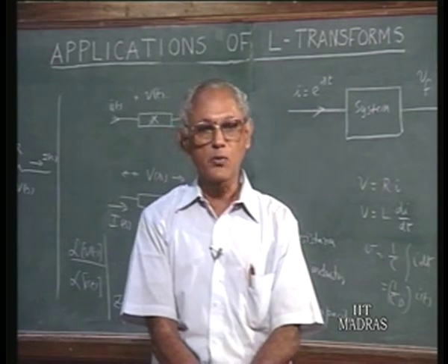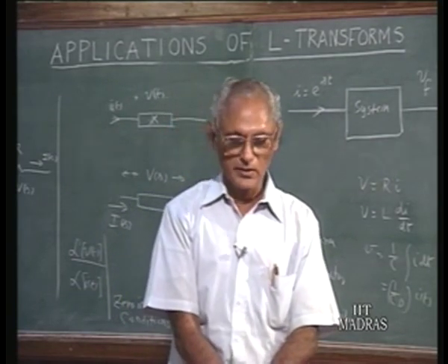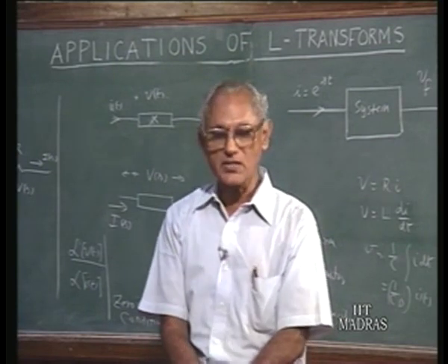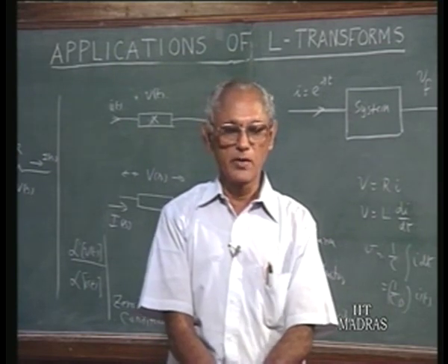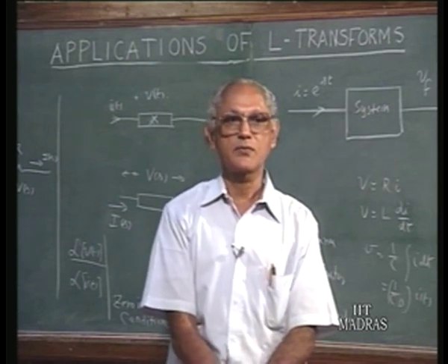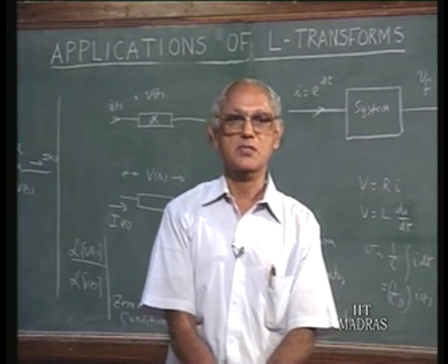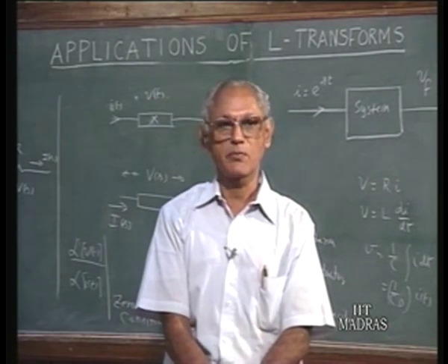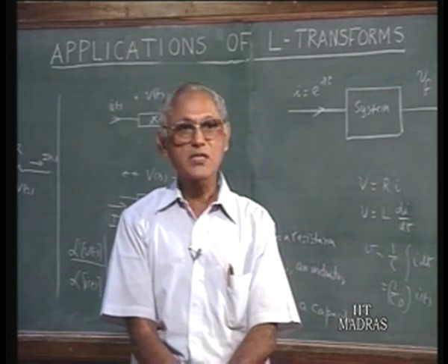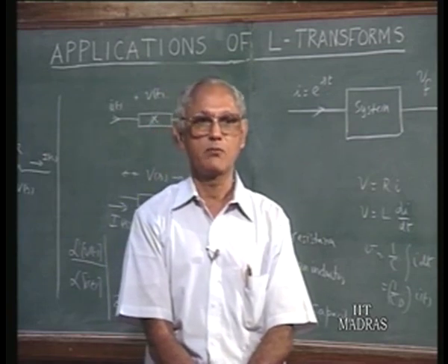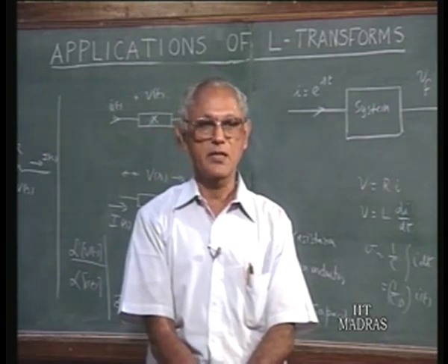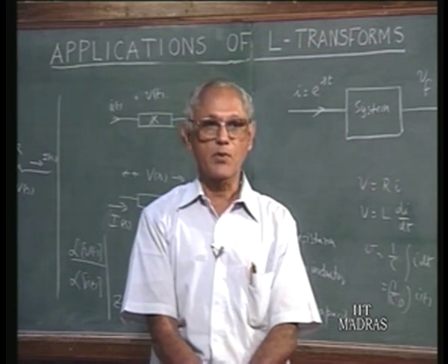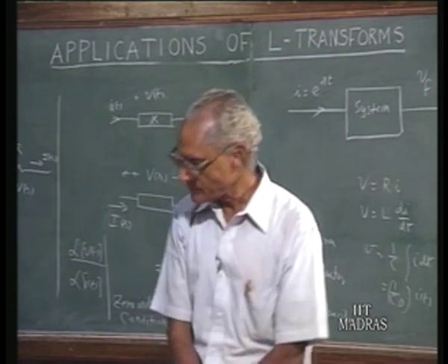the approach is very similar to what we do in the case of AC circuit analysis. We deal in terms of transformed variables instead of phasors. We deal with generalized impedances instead of sinusoidal steady state impedances. That is, wherever j omega occurs, we use S instead of j omega. That is the only difference. So this will be illustrated by means of an example which we will now take up to illustrate the technique of the Laplace transform to the transient analysis of a problem using the transform diagram.